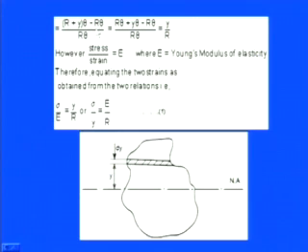So, r plus y into theta is A dash B dash, and r theta is C dash D dash. If we put these into the strain formula, we have r plus y into theta minus r theta divided by r theta, and if we simplify, the strain is equal to y by r, where y is the distance of the fiber from the neutral axis. Here it is always measured from the neutral axis, and we want to observe the effect of this bending moment on those fibers that are at a distance y from the neutral axis.